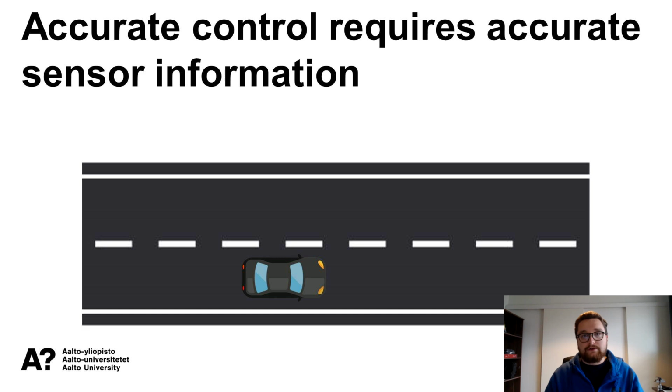If we think about our sensors, for example, if we have a camera, we are pretty much distracted by rain, snow, fog, all types of bad lighting conditions, like the sun being low there on the horizon. If you have a LiDAR, it's pretty much the same problems, except the lighting problems. If you have wheel encoders, the wheels are slipping, the information is unreliable. If we're using an inertial measurement unit, there are all kinds of bumps on the road and so on, which cause, again, flaws in that information.